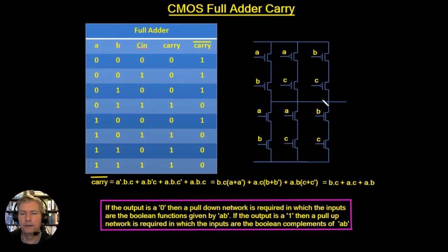So we've ended up with this structure here, and it's got 12 transistors in it. Now, as we've seen in a previous video, we could actually get rid of this transistor here, and we can connect this point here to this point, because the B is going to go through this C here. Now we could do the same, we could get rid of this transistor and connect this point over to this point. So that's going to leave us, instead of the 24 transistors, if we had worked through the full process here, with only the 10 transistors that you see here.